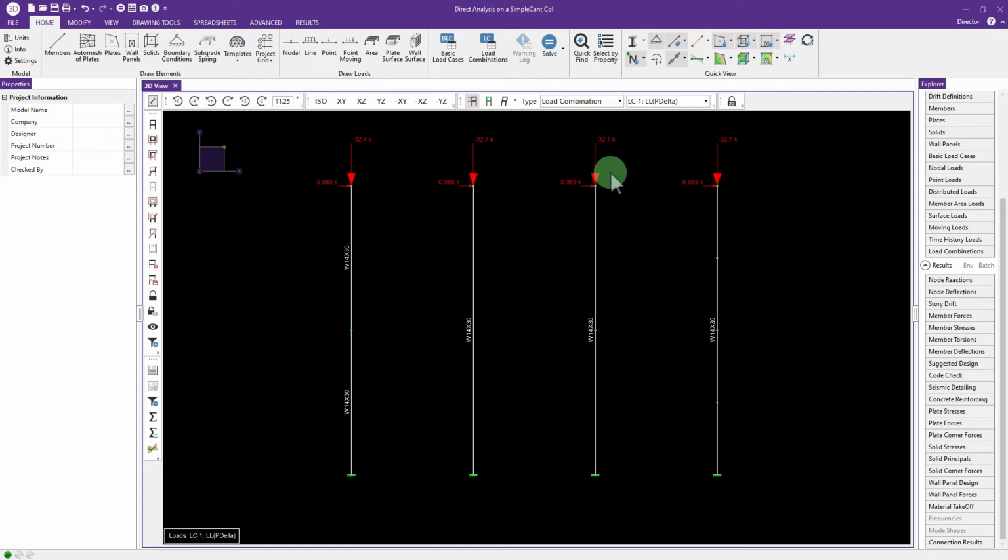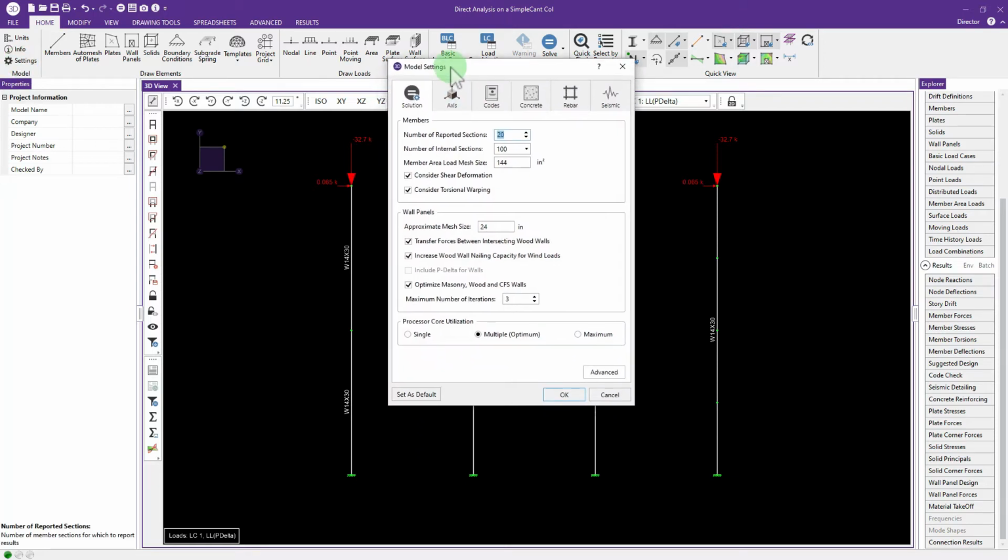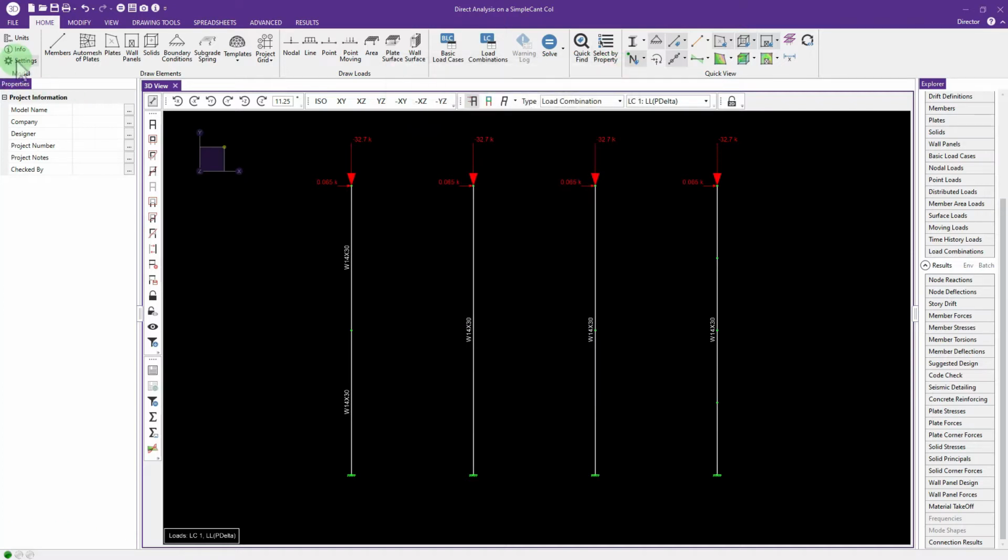So you could go back to those previous videos and see how the models are created, but what the user pointed out to me was that, of course I said I was using the previous version of Risa, and that version of Risa only had one particular methodology of implementing P-delta. That information was found in this setting right here. If you have an old version of Risa, you will go to your model settings. In the newer version, you can click on this icon here.